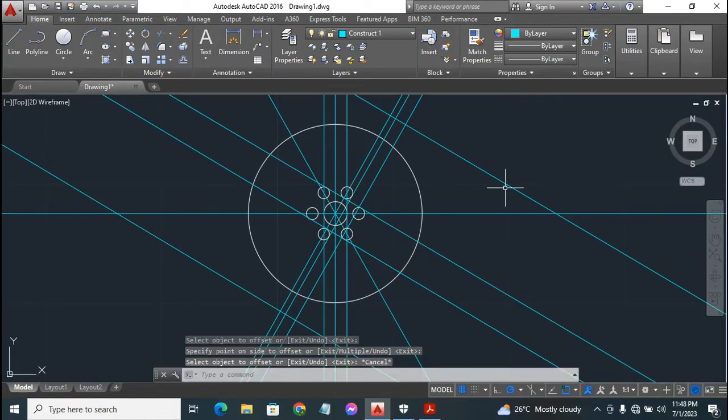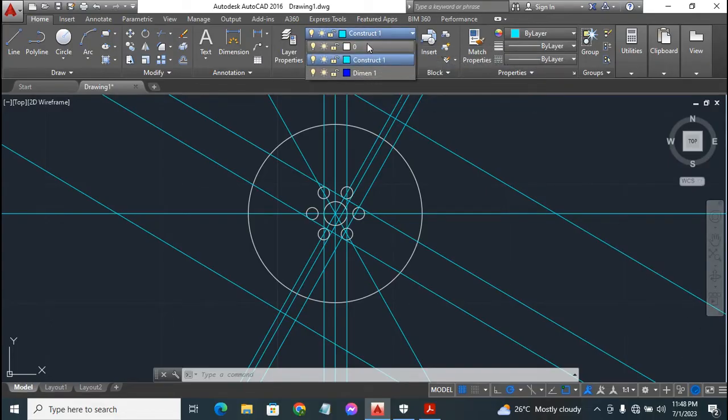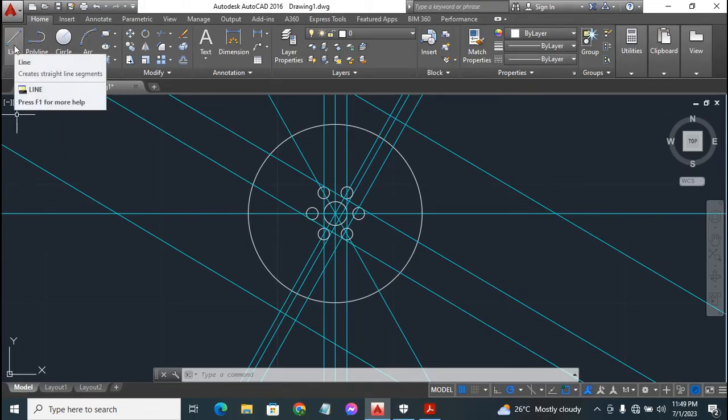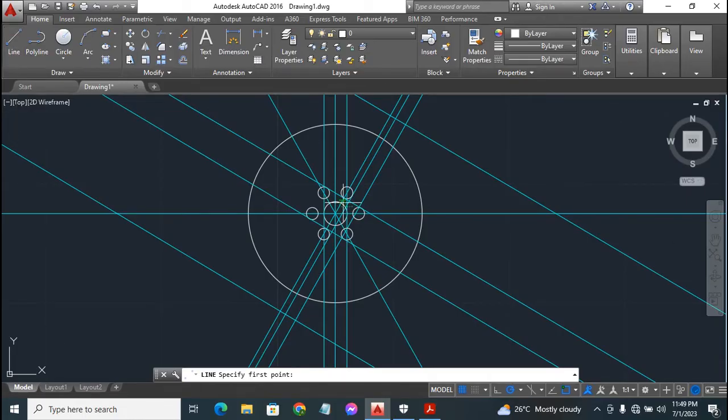So next up, we can use our main line. As you can see, this is kind of getting a little bit confusing. We have too many construction lines now. So after drawing in this extension, I'm going to start deleting off some of these construction lines so I don't get confused. Alright, so we'll go back to our main layer, go to the drop down menu of the layer ribbon, click on the 0 layer, which is our main layer. Then go back to drawing, click line. Alright, so we can comfortably draw in our extension line starting up from this point.